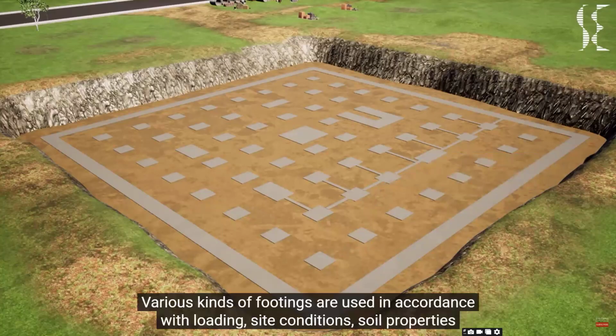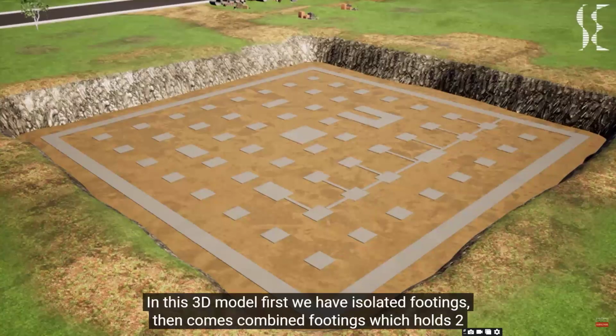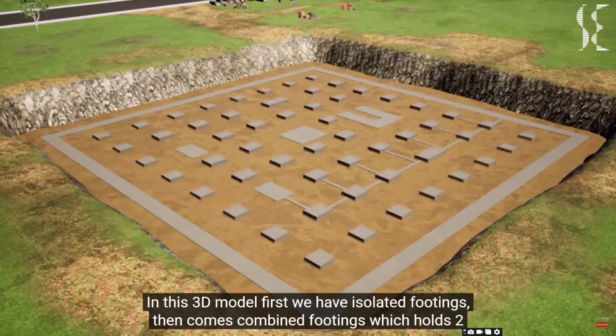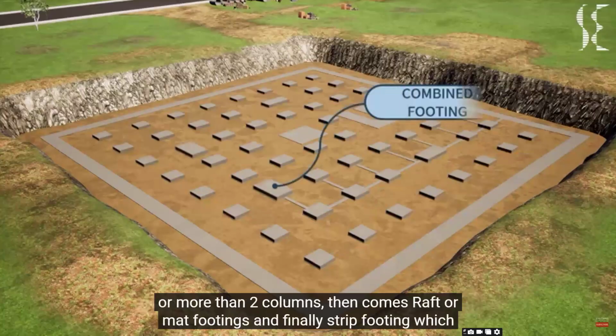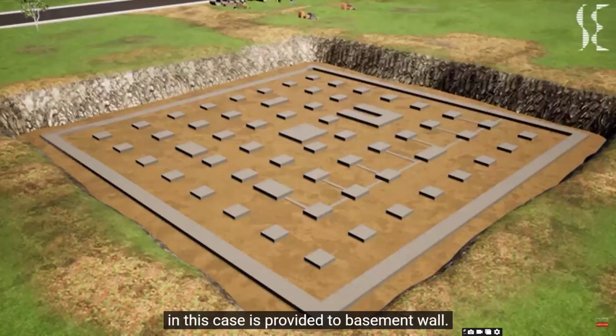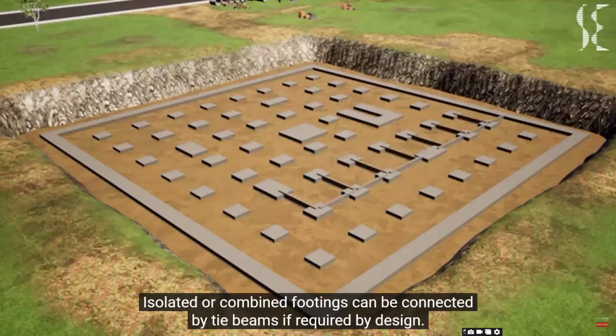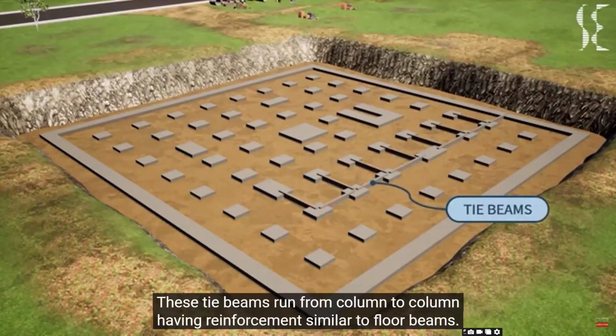ground below. Various kinds of footing are used in accordance with loading, site conditions, soil properties, and design. In this 3D model, first we have isolated footings, then comes combined footings which hold two or more columns, then comes raft or mat footings, and finally strip footings which in this case are provided to basement walls. Isolated or combined footings can be connected by tie beams if required by design. These tie beams run from column to column having reinforcement similar to floor beams.